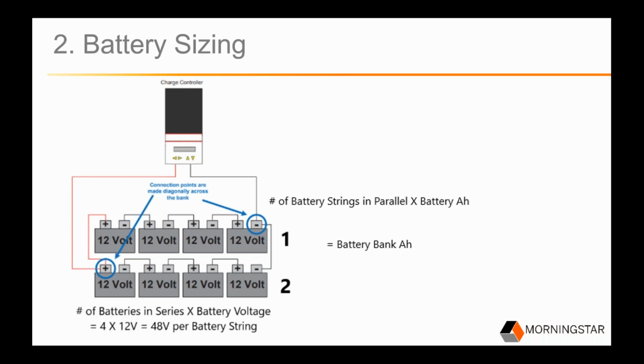Battery chemistry can affect your string sizer inputs and results. Your lead acid minimum and maximum voltages are often 23 and 30, whereas lithium minimum and maximum voltages are usually 24 and 29, and we'll see that a little bit later in this slide deck.